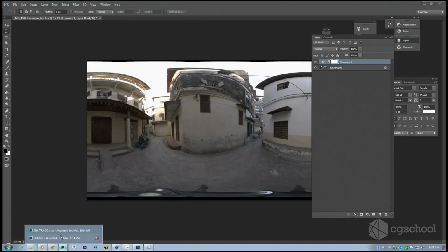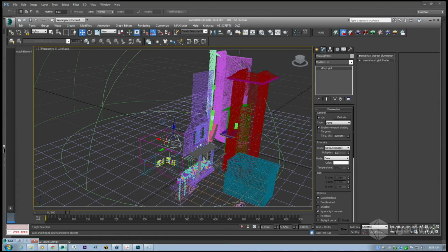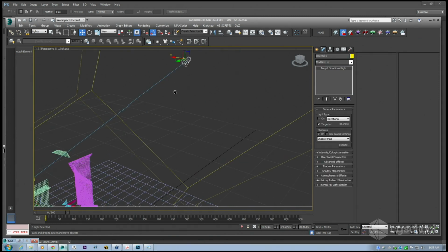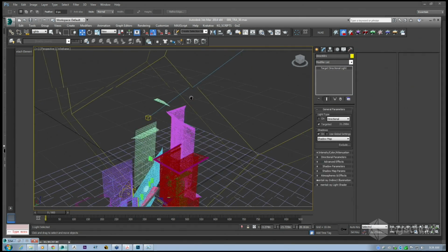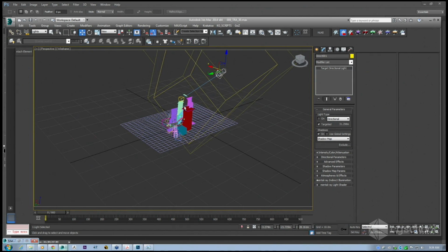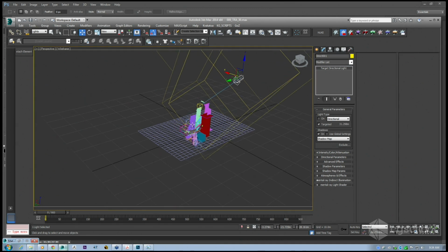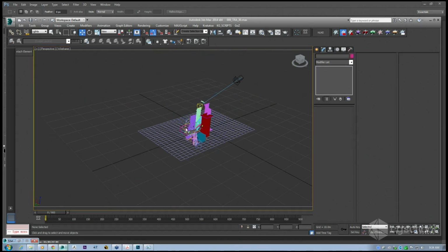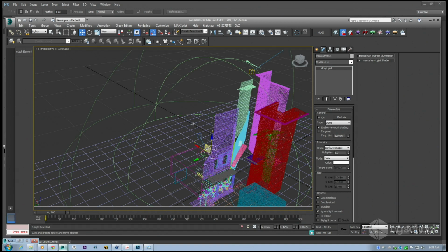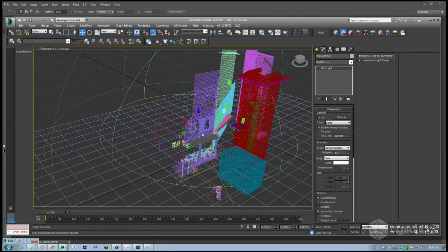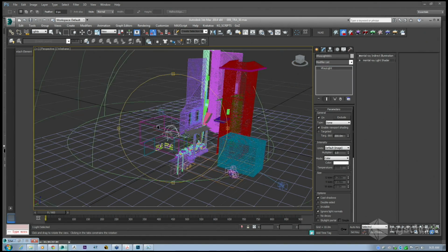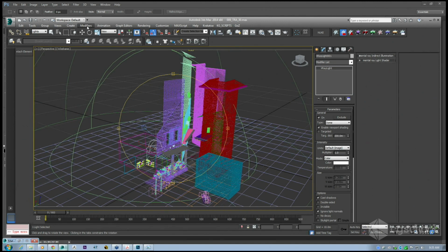You can see in the file that there was a directional light, and we did play with that for a little while, trying to recreate the lighting as accurately as possible. But we found that once we actually played around with the V-Ray light, with the settings of that HDRI, we could get it roughly working. What we sometimes do is activate V-Ray RT with nothing in the model, and just get our dome light source in the right place.